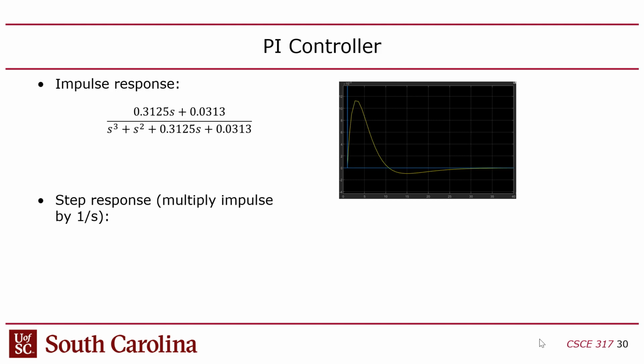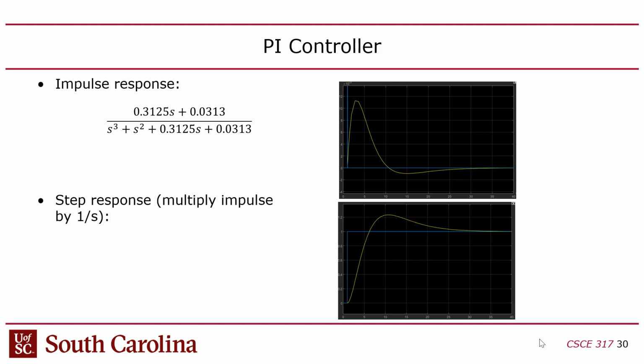But then let's think about this. What does this actually represent? What is this input? This is the set point. So this is equivalent to me telling the robot hand that's moving the coin, I want you to move the coin up and then move it back down instantly, right? And if I do that, this is the way the coin will move in response to that command to the controller. Now that's kind of a dumb command, because it would more likely be a real step response.